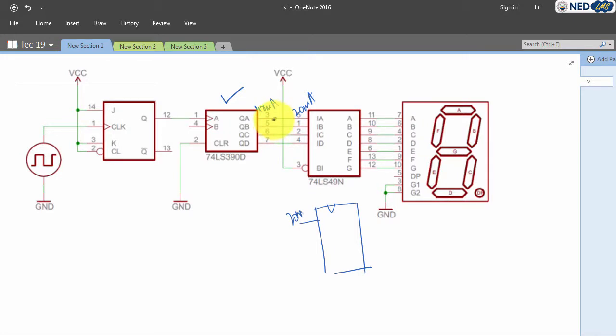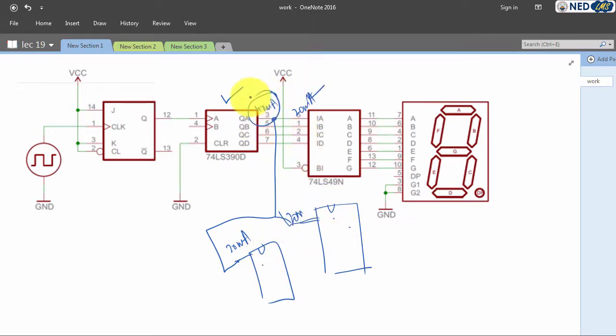So if I connect this point to this thing, that means this output can drive 20 milliamps and 20 milliamps, and that means this IC can drive only 2 inputs at this time. If I connect another IC, by IC I mean integrated circuit, which also requires 20 milliamps, and I connect this point to here as well, the requirement is 60 milliamps. We have 20 milliamps here, here, and here, but this thing can only provide 40 milliamps.